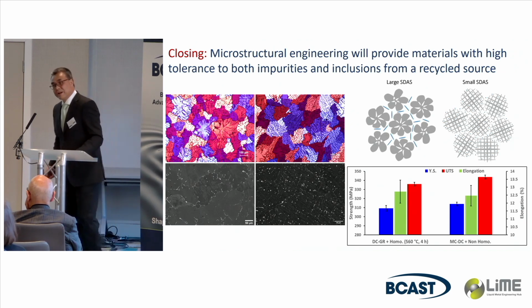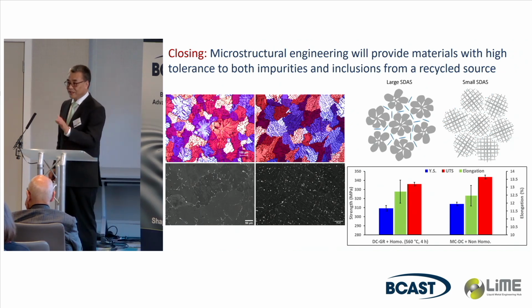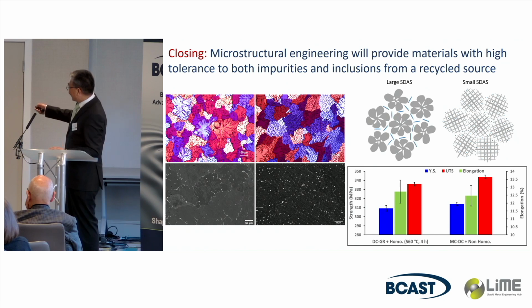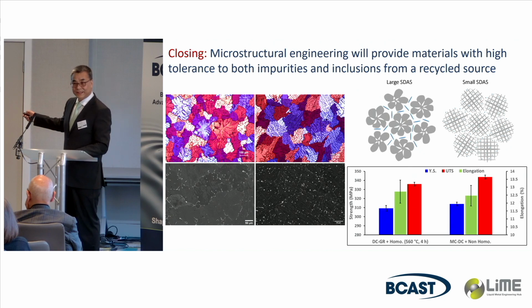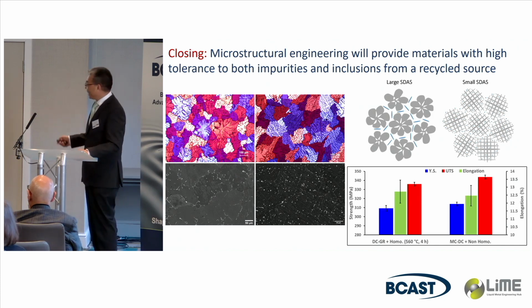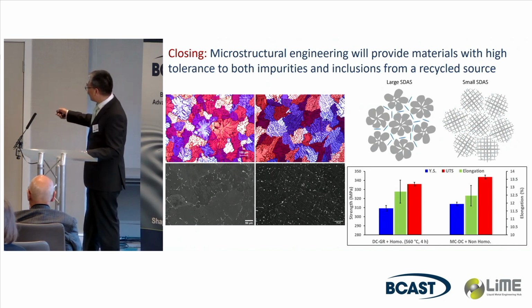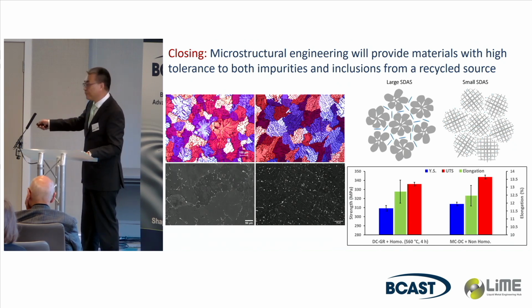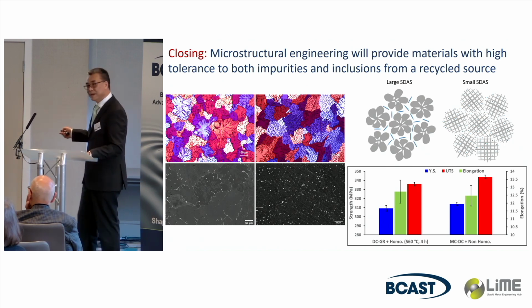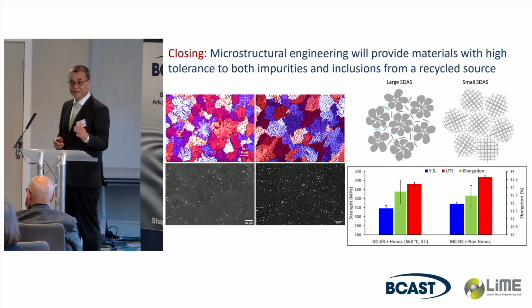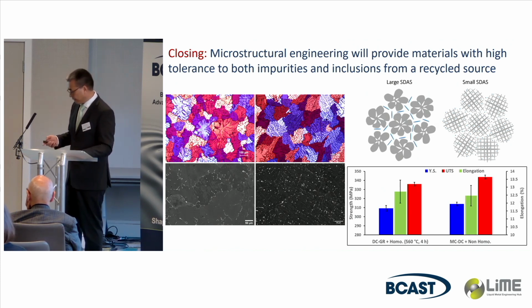The other one is microstructure engineering. We can engineer microstructures very nicely. With a grain refiner as variable use, you get so-called rosettes, equiaxed but rosettes. And you push the impurity elements like iron, aluminum, here very quickly. If you promote a reduced dendrite arm spacing, they isolate this, and eventually you can disperse second phase particles. By doing this, you can eliminate or at least reduce the homogenization process for DC casting.